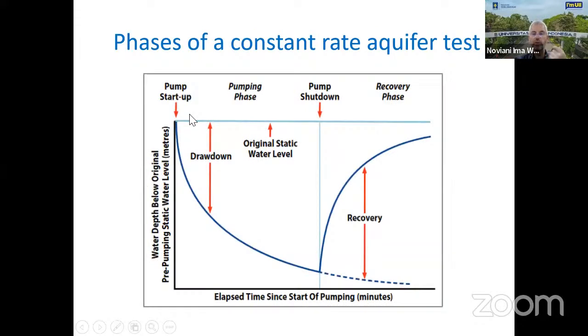So let's look at this graph for a second. At the bottom is time. Okay, here's the beginning of our test. And then time goes on. So this could be minutes, hours, days. And here's the observed drawdown. So when I start pumping, I see the water level drop, right? So the water level drops.